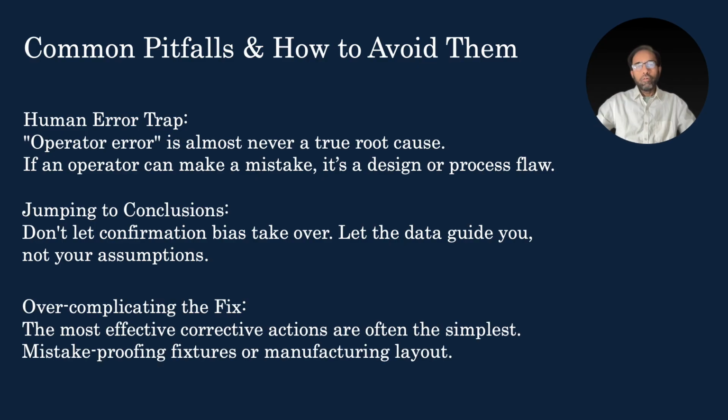Pitfall number three, overcomplicating the fix. The most effective corrective actions are often the simplest. Mistake proofing, or poka-yoke, is your best friend in medical device manufacturing a lot of times. Can you design the fixture so it only works in one way? That's better than writing a 10-page instruction manual. Remember this: design has to be the first preference, the first choice of fixing an issue.